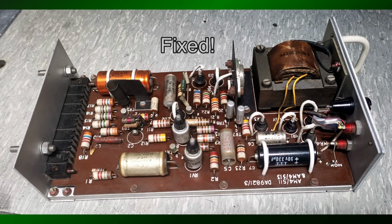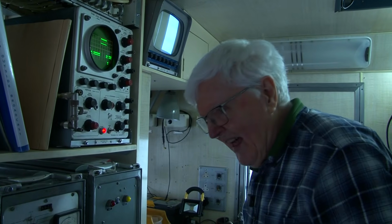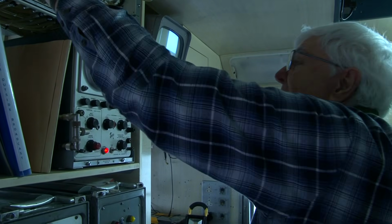I've been there professionally. Sync pulse missing on Songs of Praise. And there was a great deal of shouting and wailing because pressing the SPG changeover unit didn't fix it. And that turned out to be a faulty BNC connector on the back of the sync pulse generator changeover unit. And we fixed that with 20 minutes to go. But there we are, broadcasting's like that. Anyway, back to this.